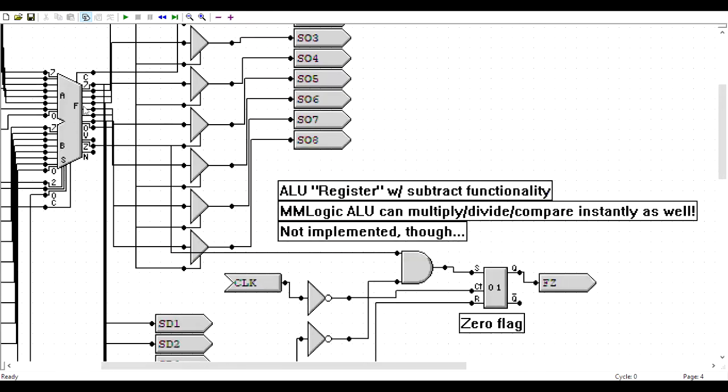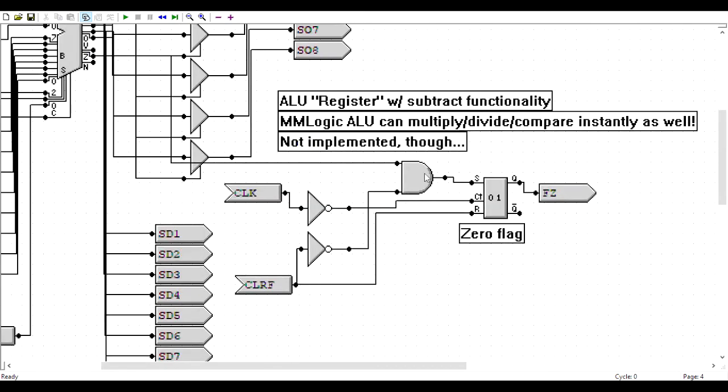You can see that the flip-flop will get updated all the time when we activate the zero or the carry flag. We're going to see this exact implementation for the top one, but we want to be sure that we have a chance to update it for real when we are doing those specific instructions. So that's why we have this clear flag.